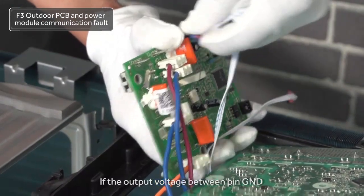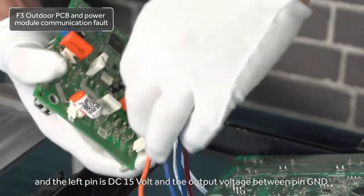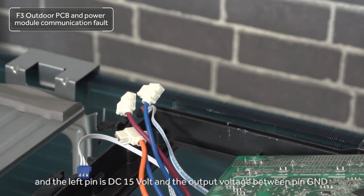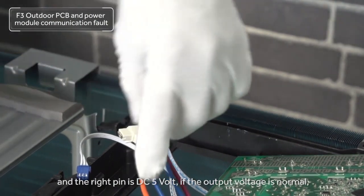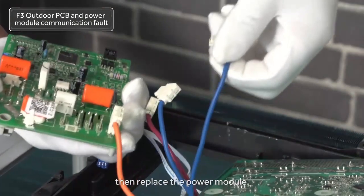If the output voltage between pin GND and the left pin is DC 15 volts, and the output voltage between pin GND and the right pin is DC 5 volts, that is, if the output voltage is normal, then replace the power module.